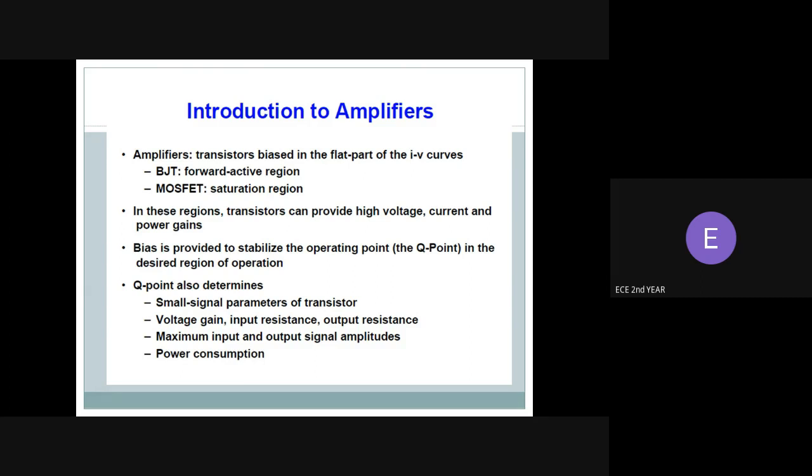The input current flowing into the emitter is quite large, as it is the sum of both the base current and collector current respectively. Therefore, the collector current output is less than the emitter current input. The current gain for this type of circuit is unity or less, or in simplest words, common base configuration attenuates the input signal.